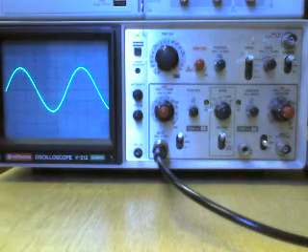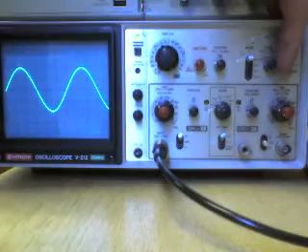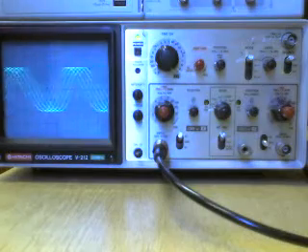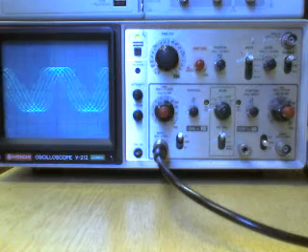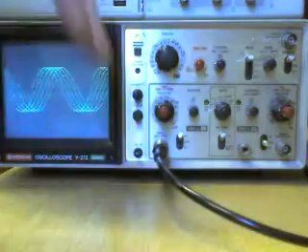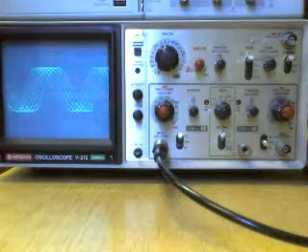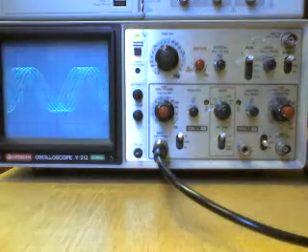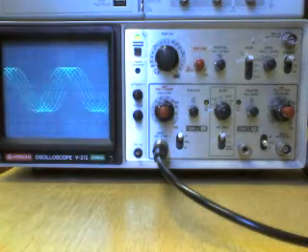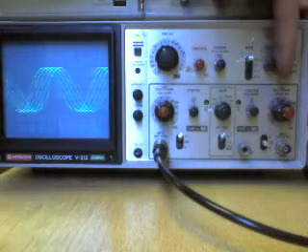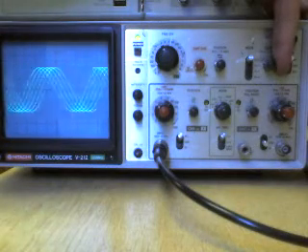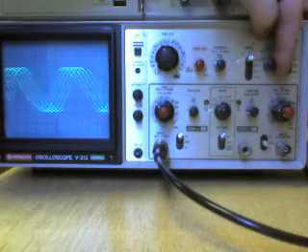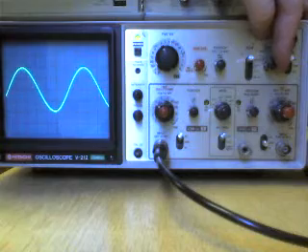Right then, so let's do some measurements. Just like I said before, we've got triggering over here. Now if our signal wasn't triggered, this is what you would see. Your sine wave is scrolling across the screen because it's a continuous wave. Okay, it's continuously moving in time across the screen. It started at this point, it's just shot straight past, and it's somewhere in the past now. So what you need to do is, because it's a continuous wave, it's always starting and stopping at the same point, it's repetitive. What you can do is you can trigger by turning our trigger knob.